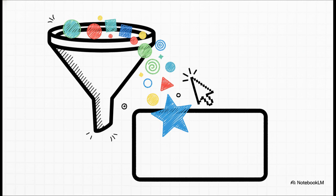Once your inputs are primed for that 800 nanosecond chunk of time, highlight your expected outputs, which are sum, carryout, and overflow, and drag them straight into the wave window. And just like that, your test bed is fully loaded.